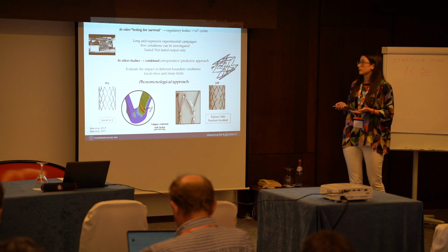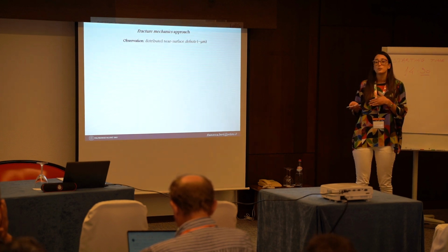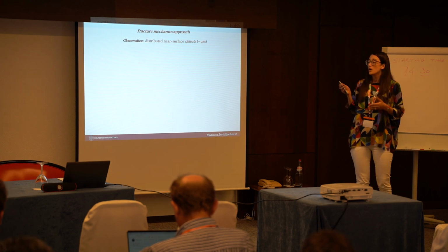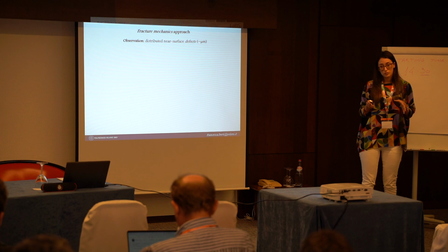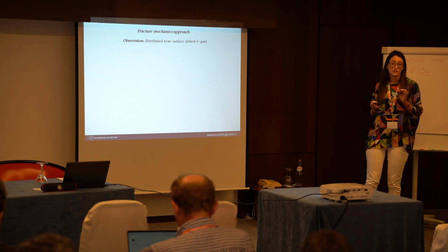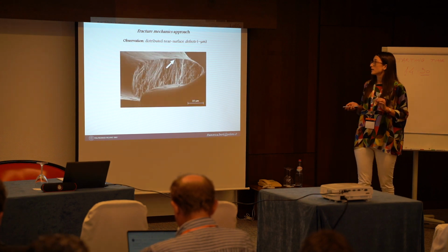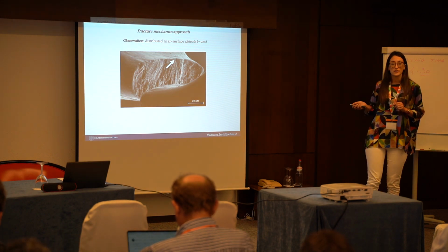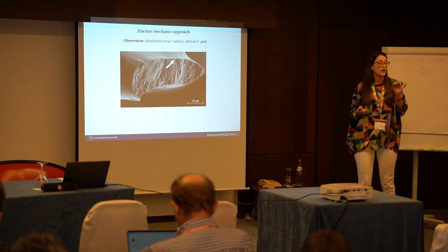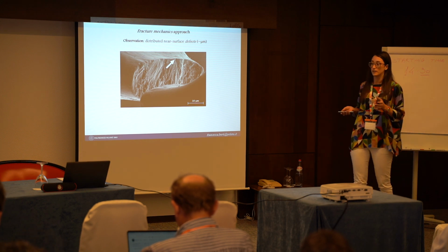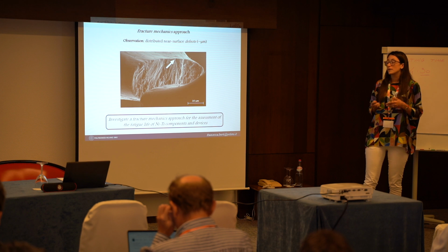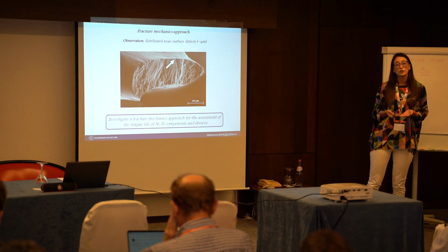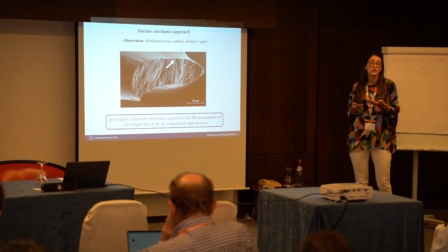To go further, to complete this study, we wanted to take another way, a more local one. We observed that on the stent surface there are defects on the order of microns. And if we look at the fracture location, this is a fracture of a stent, we can see that sometimes cracking is initiated at these defects. For this reason, we decided to investigate if a fracture mechanics approach could justify or interpret this failure in the stents.